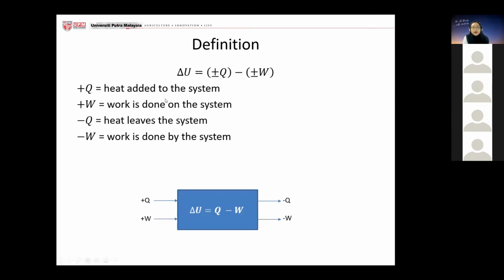Now, this is also very important: the convention of signs for heat and work. Anything that is added, if you add heat to your system, will be considered positive. Or if work is done to the system, it's positive. But if the heat leaves the system or the system itself does work, that will be designated as negative.